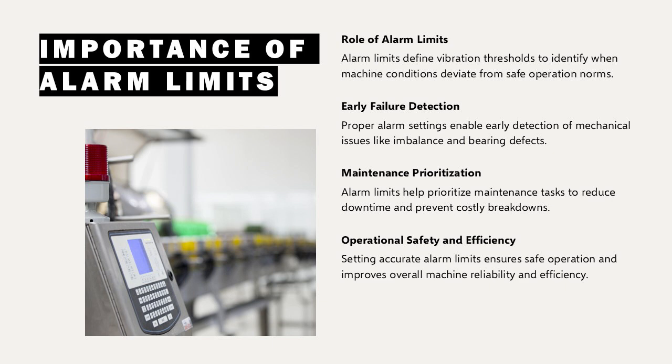They serve as thresholds that indicate when a machine's vibration levels exceed acceptable norms, signaling potential mechanical issues such as imbalance, misalignment, or bearing defects. By setting proper alarm limits, analysts can detect early signs of failure, reduce downtime, and prevent catastrophic breakdowns.